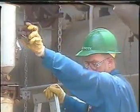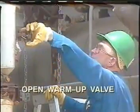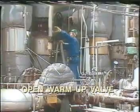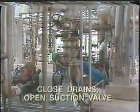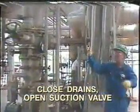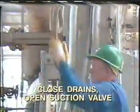If the pump is used for hot liquids and is not always kept at operating temperature, open the warm-up valve. This may prime the pump as well as warming it. When the pump is warm, close the valve. Next, close all drains and open the suction valve to the pump. Then prime the pump. Be sure the priming is complete before starting the pump.